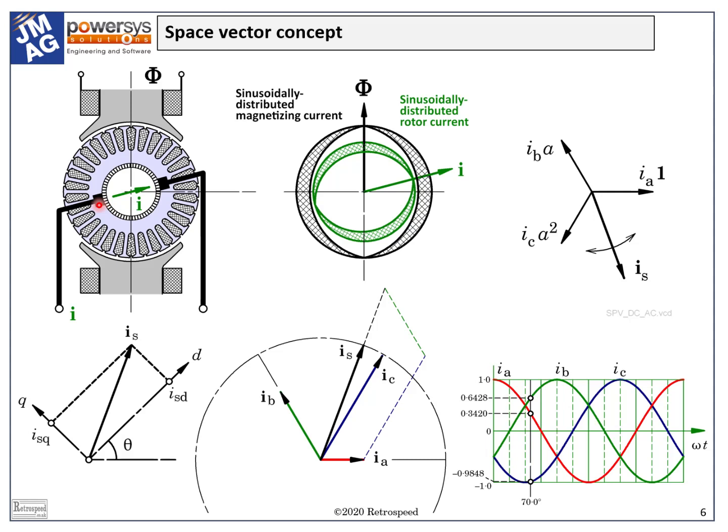Even though the armature conductors are rotating, the direction or orientation of the pattern of ampere conductors is actually fixed in space by the action of the commutator and brushes. By rotating the brushes, we can alter the orientation of the armature current and thus control its effects.